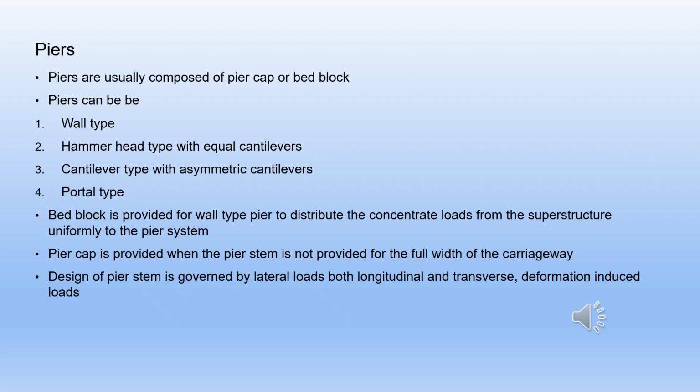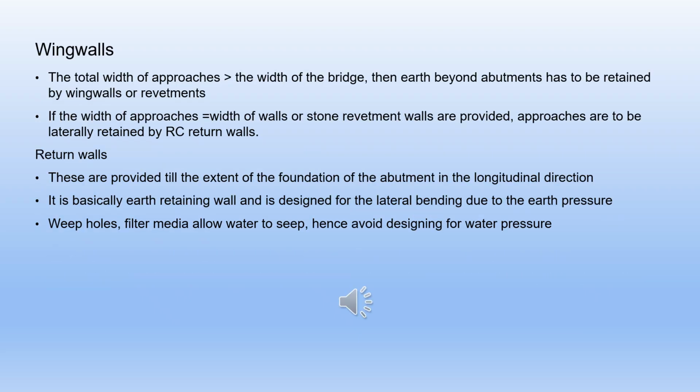The design of pier stems is usually governed by the lateral loads, both longitudinal and transverse, arising from wind, seismic, braking, traction, centrifugal, and deformation-induced loads due to creep, shrinkage, temperature, settlement, etc. The total width of approaches is usually greater than the width of the bridge.